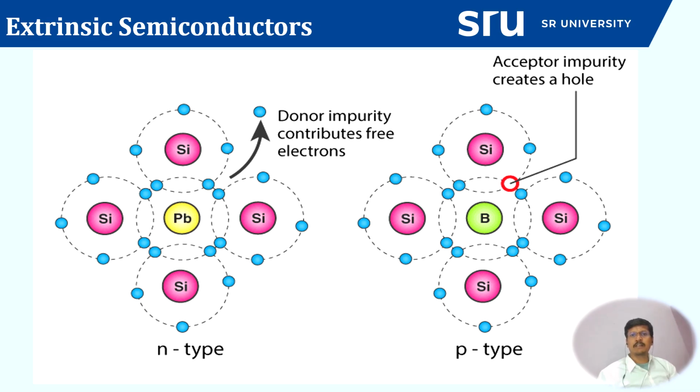In P-type semiconductors, doping creates additional holes, because in P-type semiconductors we introduce trivalent impurity atoms, which have only 3 electrons in the outermost orbital. Those 3 electrons form bonds with 3 neighboring atoms, and one vacant position is still available.